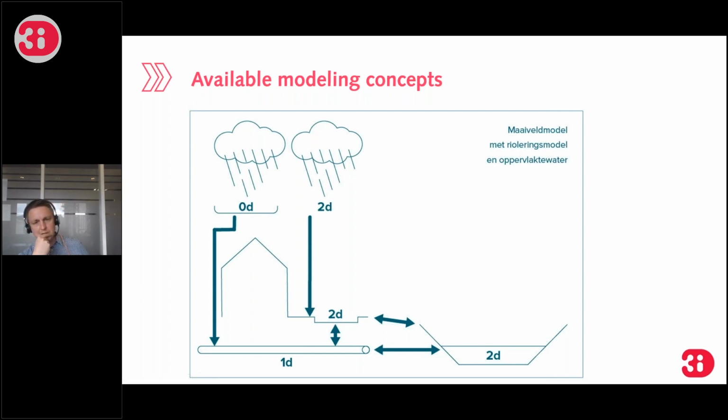Well, there is no right or wrong, but I myself would prefer it simply as an overland flow simulation. And for the channels, you can either use a digital elevation model including bathymetry, or you can use a cross-sectional profile in the channels that you get in the data directly from, for example, the government that is managing this area. So what does that look like?